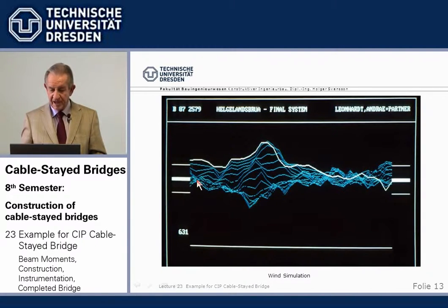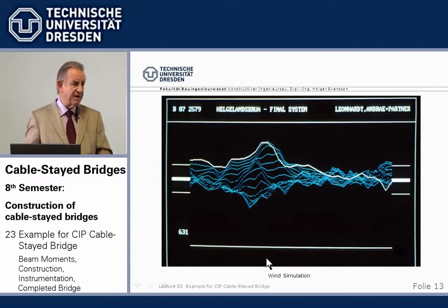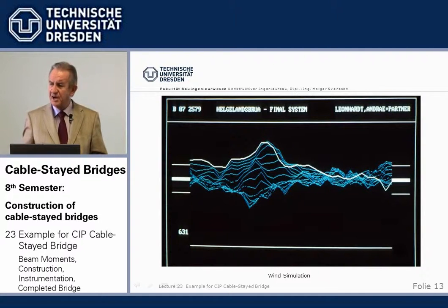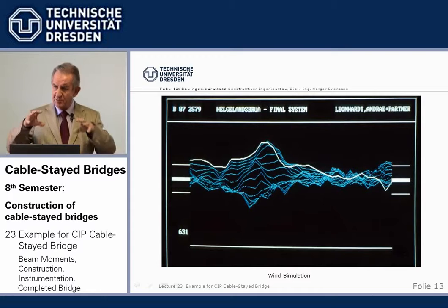Then over the length of the bridge, we create a wind climate. These are 0.2 second steps of how the wind changes. There are 6 runs of, I think, 200 seconds or so, where different wind climates are created, which are placed onto the bridge, this theoretical wind, which is okay in the boundaries as measured on site.